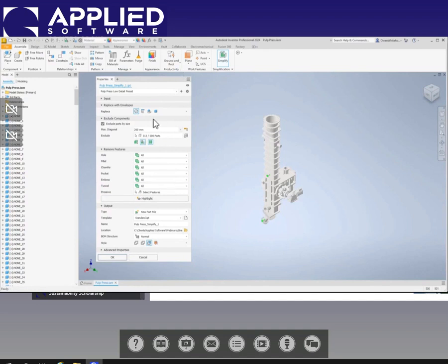And so rather than having to configure all this again, what I like to do is hit this plus, and it's going to allow me to save a new preset. So sometimes if you know that this is going to be, say, MX 1001, you could say this would be a low detail, and you can save that now. And so now we've got a very focused set of configurations to strip the detail out of this particular model.